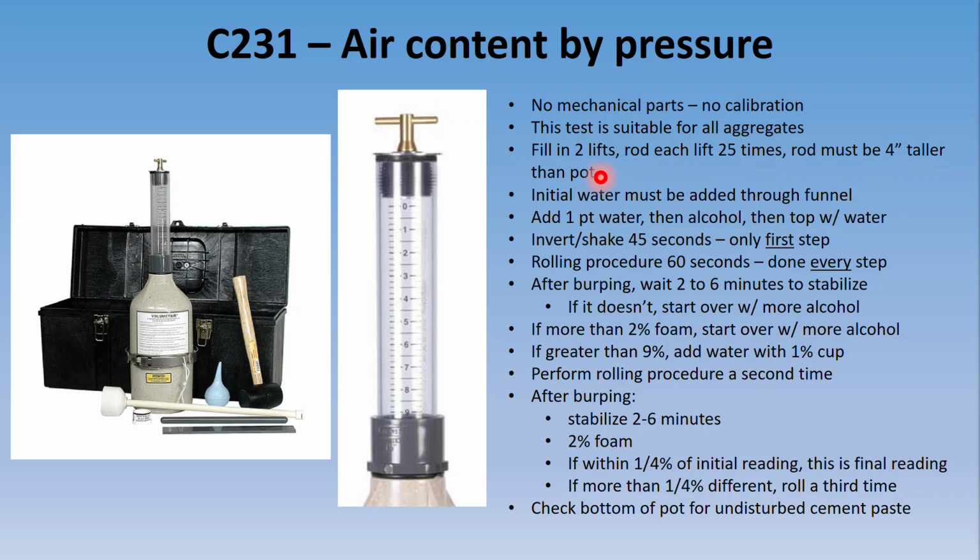And another step that people kind of forget to do is that once you've filled up your pot in those lifts, you've struck it off using your strike bar, you really want to clean that surface. You saw that in the video. He really took time to take a sponge in his fingers and clean off that lip, because you want to make a good seal between the pot and the gasket on this upper chamber.